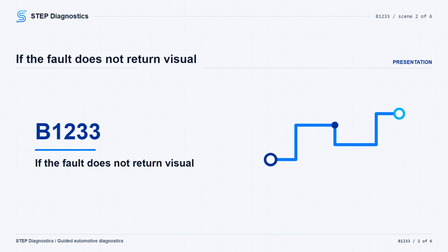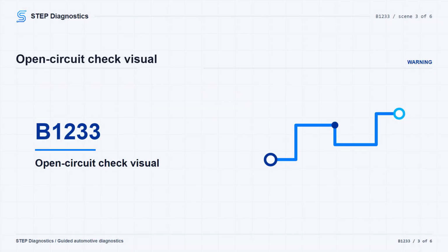Do not jump straight to parts. Work the air mix control motor circuit for loose wires or poor connections, especially anywhere the harness or connectors could be disturbed. If the fault is indicated again, move into the open wire check.